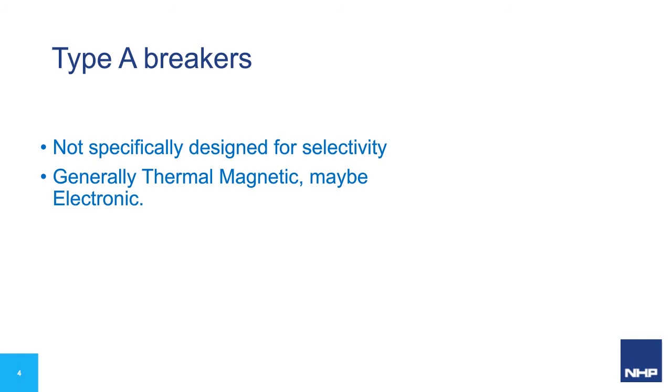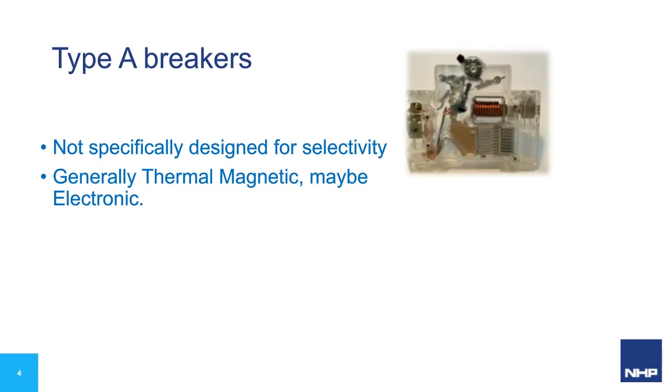Now let's not complicate the issue with this clause and table 3, except in short to say that the clause defines the meaning of ICW or short time withstand current. Now short time withstand current is the rating of current multiplied by time that a device needs to endure before it becomes a current limiting device, as in it begins to open.